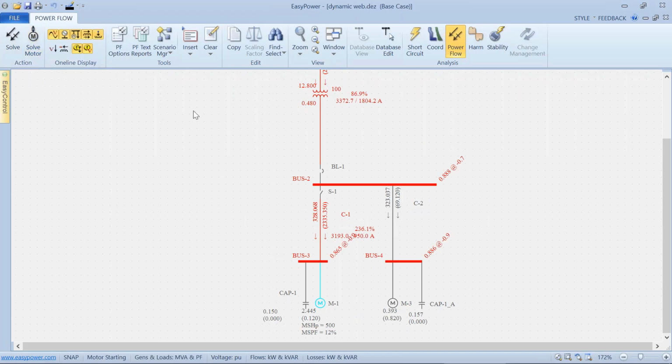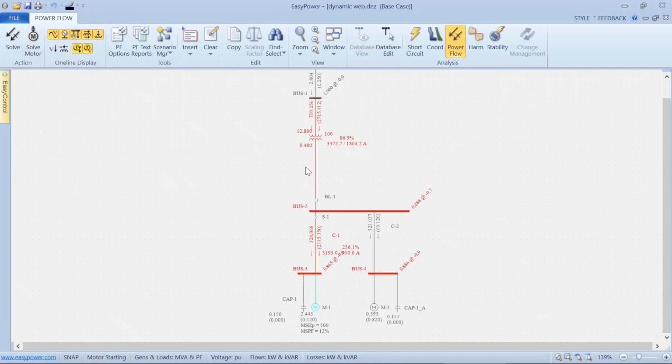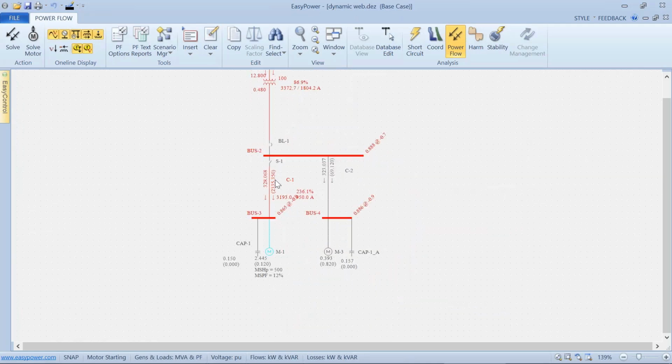And by starting that one motor, I can see I have, at least for some period of time, albeit relatively quick, some significant losses and overcurrent situations and voltage drops on the near-term buses.